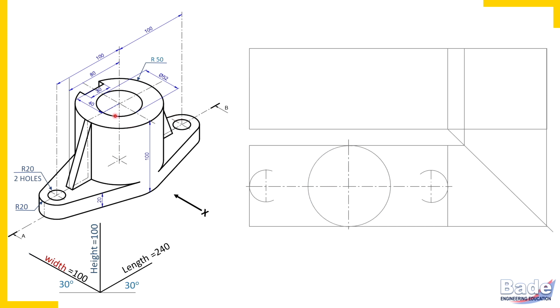Right now we don't have any intention to draw the cylinder. We are just drawing this plate. Because the boundary edges of the plate meet the cylindrical surface tangentially, that is why for reference we have drawn this circular edge. Now draw tangents to these curves. So this edge which is on the back side, non-principal edge, I have drawn. Similarly, draw other tangents to the curve. And this is how you will realize how much portion of these faint curves are at the boundary, and make them dark.